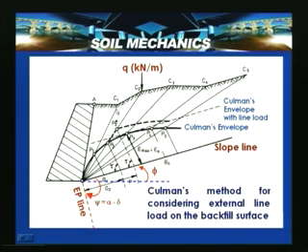And here what we need to do is draw the geometry of the wall, and this geometry has to be represented, and the ground surface has to be drawn. First the slope line has to be drawn with angle phi above the horizontal, and the earth pressure line has to be drawn, which is psi equal to alpha minus delta.